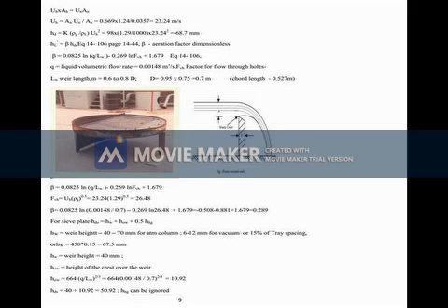That is total. How many holes are there? We don't know. The total area is given as 0.357 meters square. Then assume one hole diameter is 10 mm with an equilateral triangle pitch. What is pitch? Pitch is the distance between the centers of the slots or sieves. Area of one hole is pi by 4 d squared, which comes around 7.85 into 10 raised to minus 5.